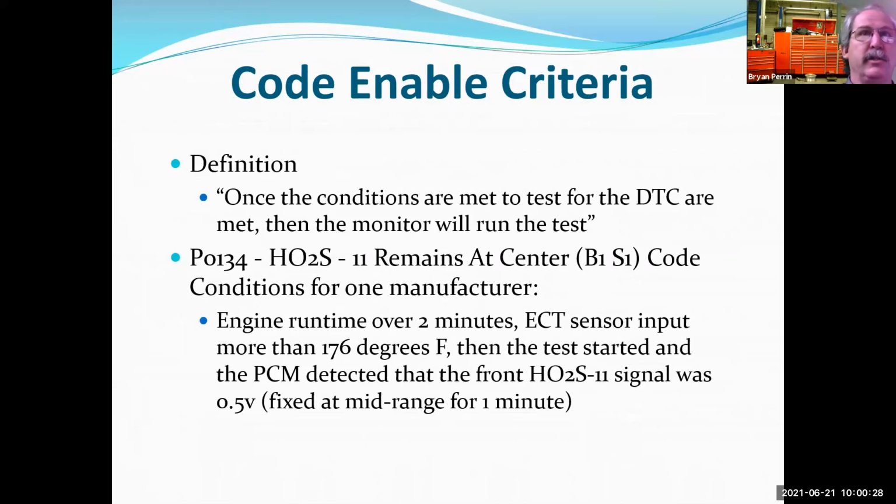So my next question is, because we have a monitor for testing the oxygen sensor heater, was the heater tested? If the heater was tested and passed, it should be coming active on time. If the heater wasn't tested, or I don't know if it was tested because someone cleared all the data, now it might have just not been warming up, and I might have a bad heater, but I don't have a code for the heater because someone already cleared that, and now it can't test it.